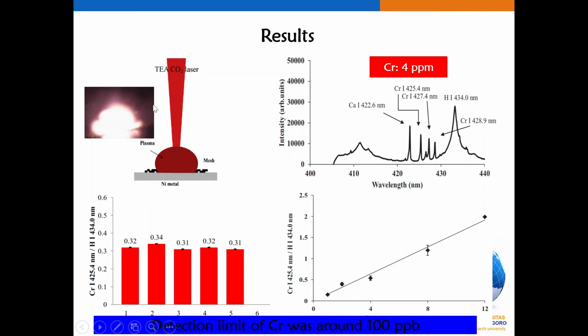Also, it should be mentioned here that by using our vaporization technique, the silicon itself is never ablated because we use a vaporization technique by defocusing the CO2 laser beam 5 millimeters on the silicon surface.